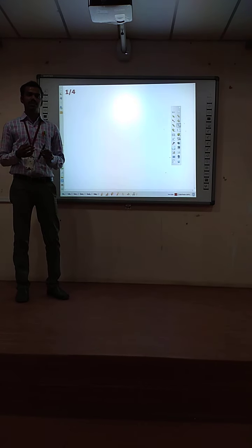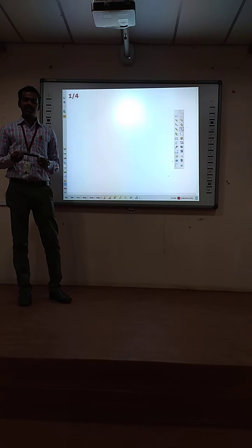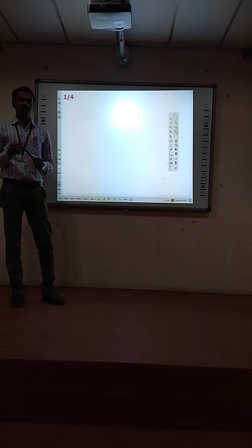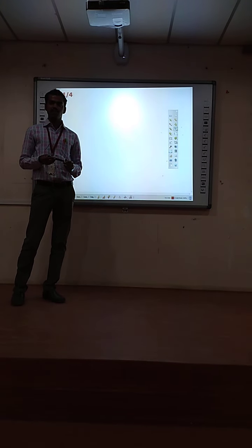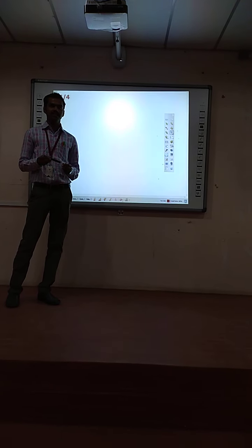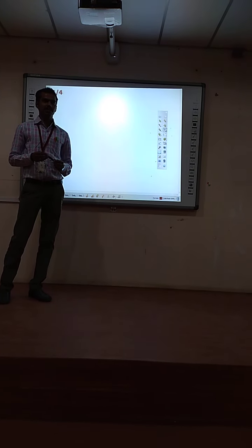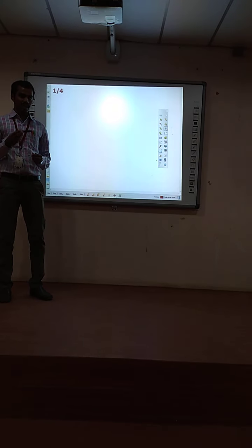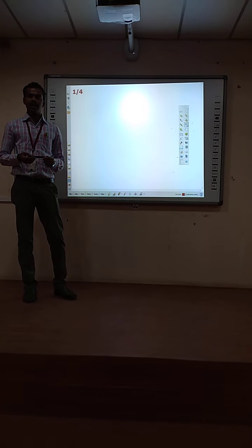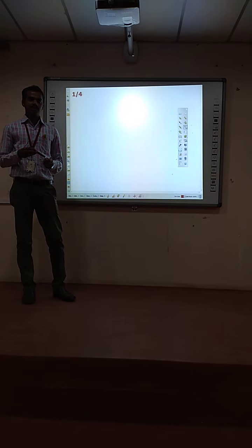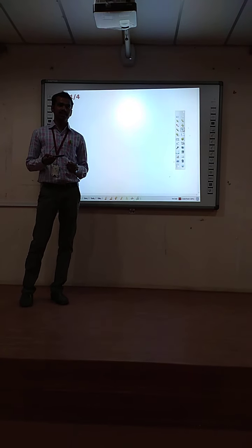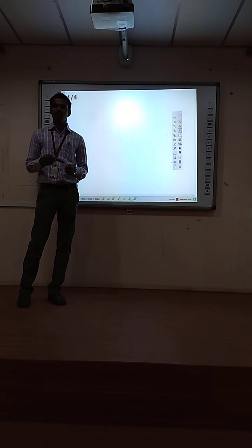So first, determinate beams are nothing but we have solved the equations by summation of horizontal forces and summation of vertical forces and moment. These three equations are equilibrium equations. So based upon that, we solve the problems and find the bending moment. In indeterminate beams, these three equations are not sufficient to calculate the bending moment.